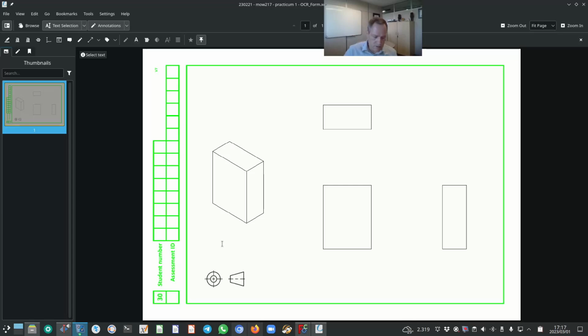What I suggest you do, so you will see this is the isometric view. We're not going to dimension this view. We're going to dimension the front, top, and right view. And it's good practice, if you have a view on a page, to put a dimension on that specific view. Otherwise, if you just have a view with no dimensions or no datums identified on that view, it's pointless to have the view on your drawing. So with that strategy, I will now dimension this drawing.